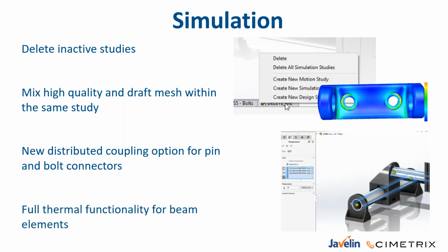On top of all of this, we're seeing some nice general improvements to the solvers in SOLIDWORKS simulation for multiple load cases. In SOLIDWORKS 2019, there was a bit of this, where for multiple load cases in certain situations, it would not repeat the discretization and factorization of the stiffness matrix. It is now going to be faster when you're using multiple load cases with remote loads as well. But just keep in mind, it is not going to be faster if you have the no penetration or virtual wall restraints in there, okay?